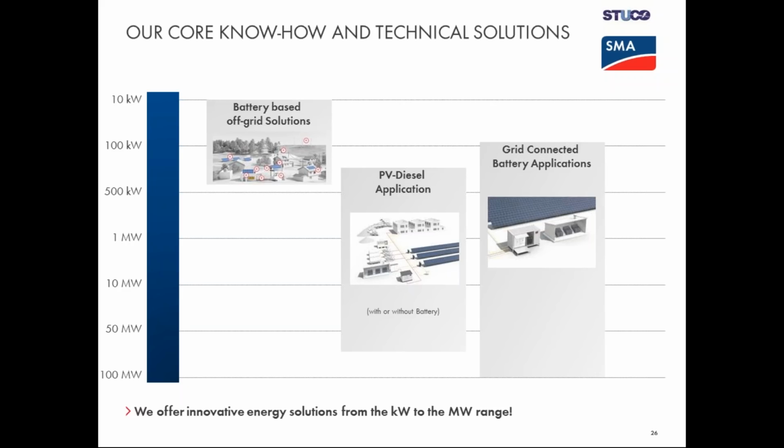You can also look into the addition of energy storage to cover a large time of autonomy. Typically in such systems, you can size the system to have a couple of days of autonomy, since the investment may not be significant, still talking about the kilowatt range.